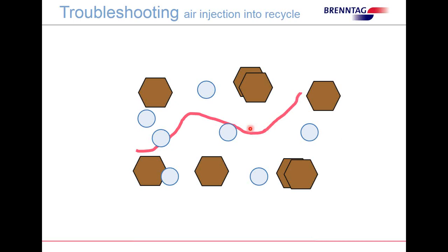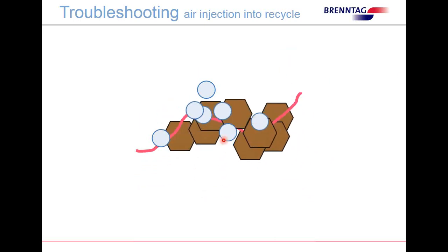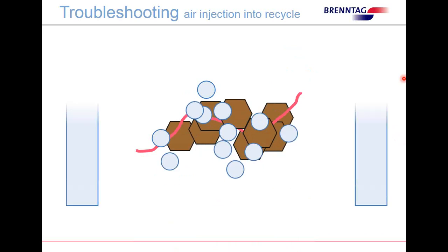Consider when you add your flocculant at the same time there's air present along with the pin flocs. So what happens is now you entrap air in the floc, so when it does come into the system, you have your typical air from the bottom, and you get a quicker, faster, more efficient removal. I'm a big fan of trying to add flocculant into the recycle.